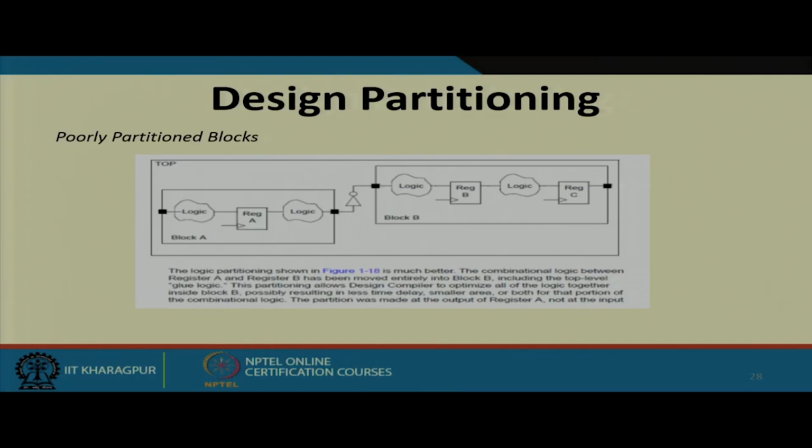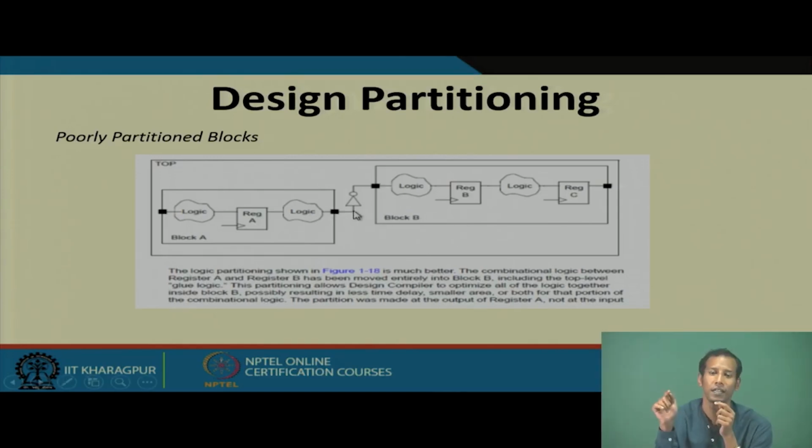They will be interconnected, but whenever we place them inside of the core, the FFT blocks whose cells are required together will be placed closer to each other. Why? Because if I place one cell of the FFT in one corner and another cell of the FFT in another corner, the net delay will become too long and it will unnecessarily increase the cycle time or the critical path.